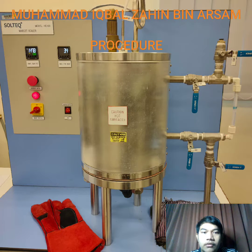I will tell about the procedure of the experiment with the Marcet boiler. First, fill up the boiler with water to a certain level. Next, if the boiler is initially filled with water, open the valves at the level side tube, V2 and V3, to check the water level. Pour in additional distilled water if necessary, then close the valves.